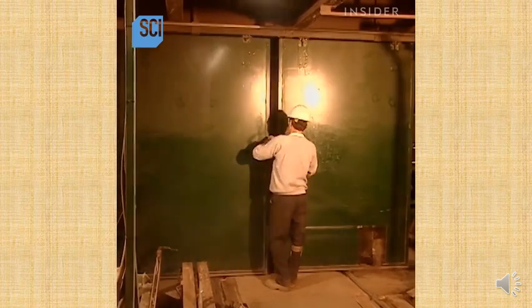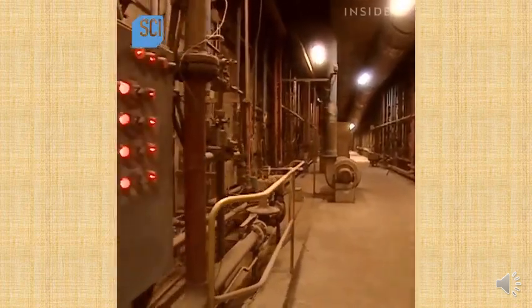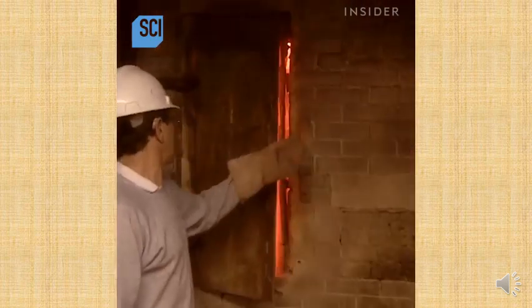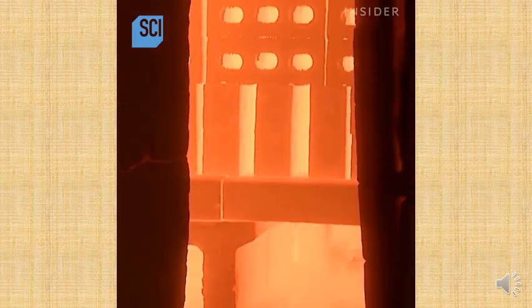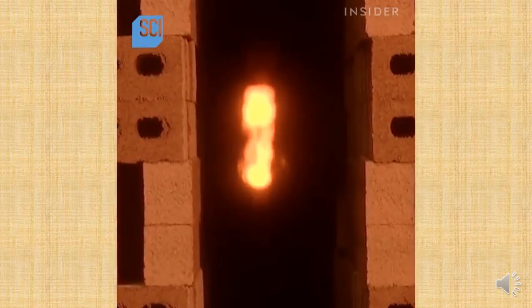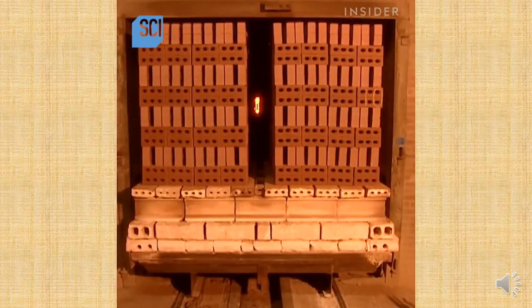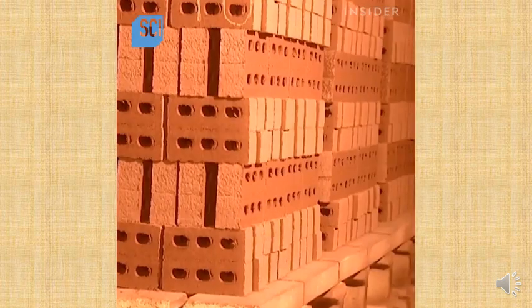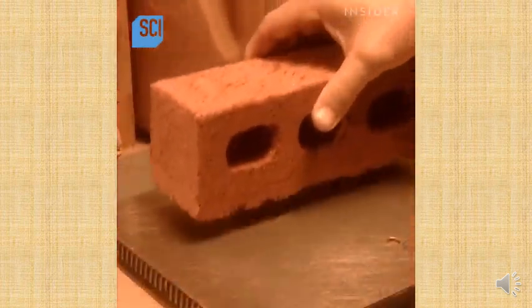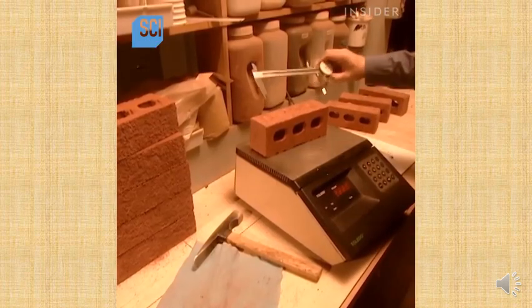The kiln is really a giant oven. It bakes the bricks at 1,040 degrees Celsius. That's almost 2,000 degrees Fahrenheit. One and a half days later, the bricks are ready. The transfer machine takes them out of the kiln. But before they go to market, a technician does a quality check. He weighs and measures a sample to see if it meets the design specifications.